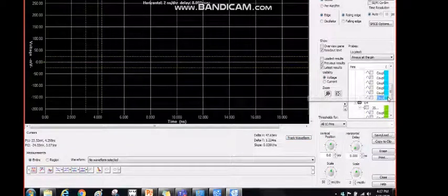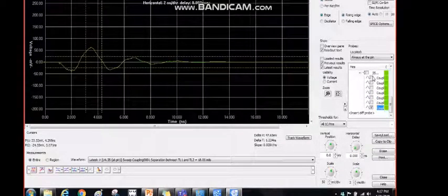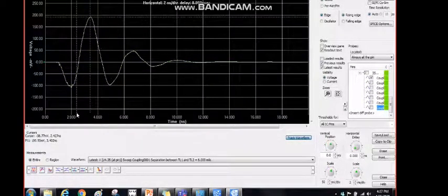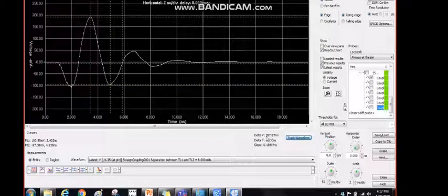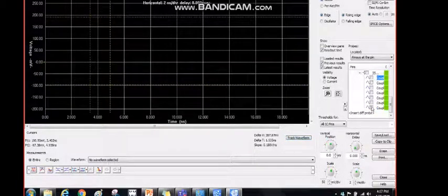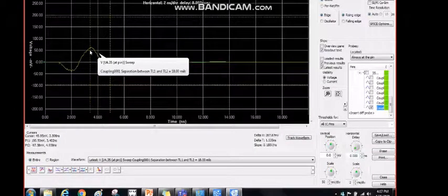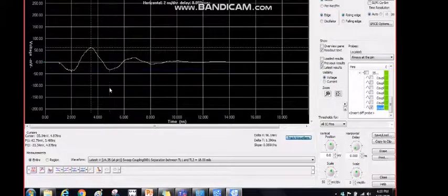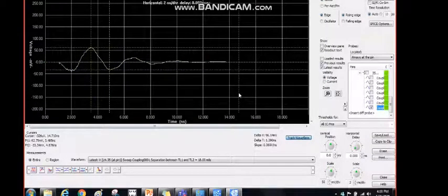So let me only take care of the maximum distance. Okay, let me first calculate the minimum. The minimum would be somewhere close to 287 millivolt, wherein at the longest distance between these two, the crosstalk at far end would be 96 millivolt. But making these changes may not be possible every time.